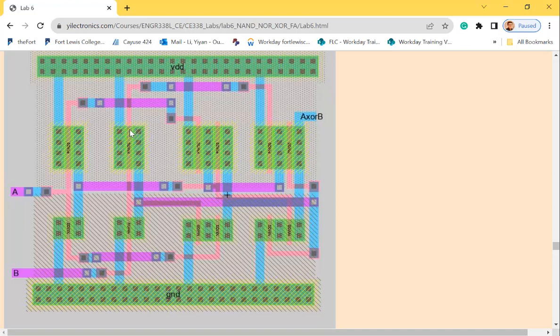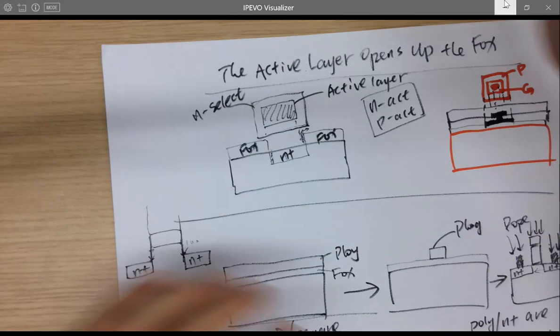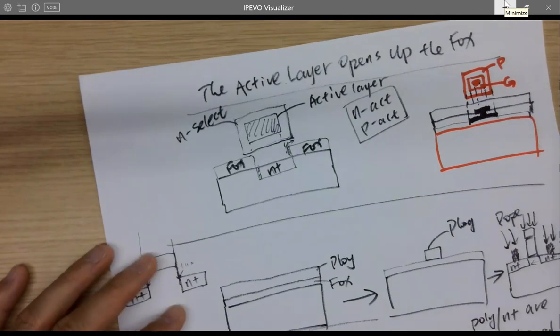So these two gates are connected: I introduce a via and connect to metal 1 and then metal 2. You can imagine how that works. It goes from poly to this, to this. That's how I connect them instead of using poly. Does that all make sense? Okay.